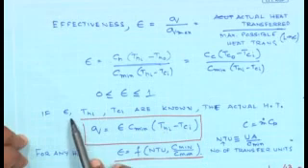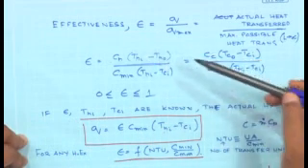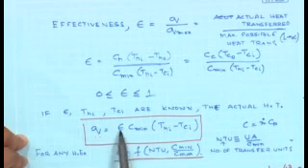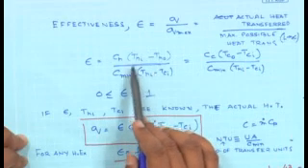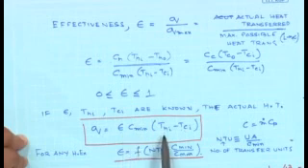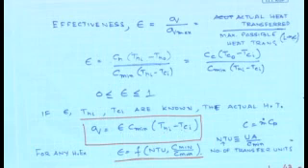And if we know the value of epsilon, the value of Thi and the value of Tci, then the actual heat transfer is simply going to be Q equals epsilon C minimum (Thi minus Tci). That's the total amount of heat transfer. Since the epsilon-NTU method is used when the inlet temperatures are known, so Thi and Tci are known to me, and therefore it is possible to calculate the actual heat transfer, based on the difference of the inlet temperatures, provided epsilon is known.